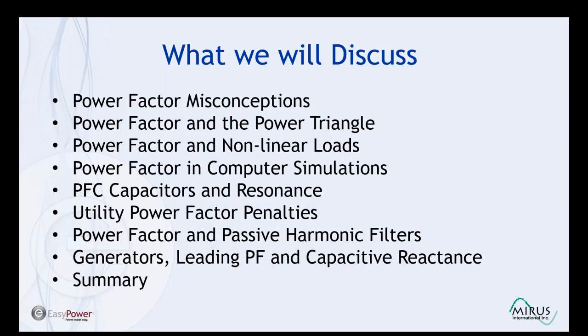And then the use of power factor correction capacitors to improve power factor will be introduced, with a focus on their potential for resonance with the power system and their ineffectiveness when the low power factor is caused by harmonics.